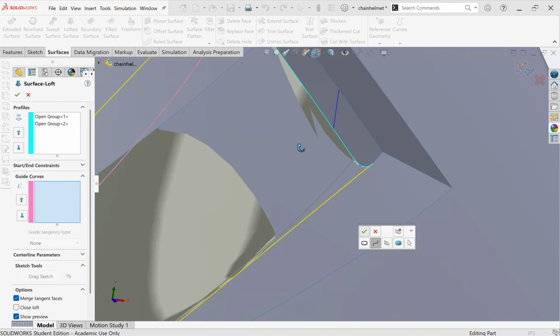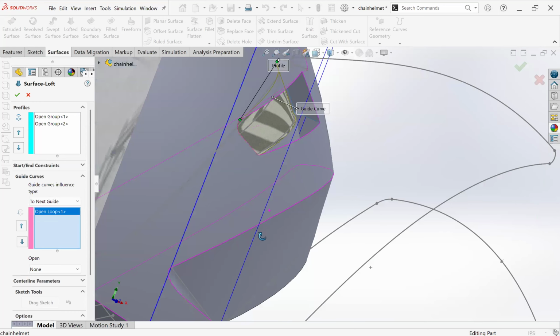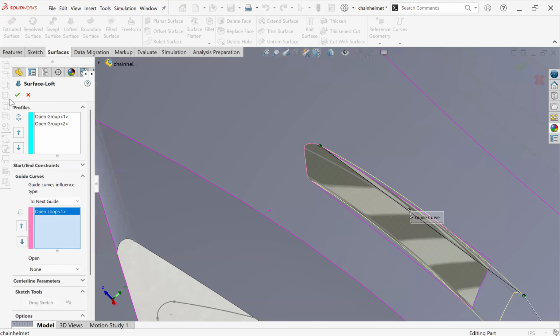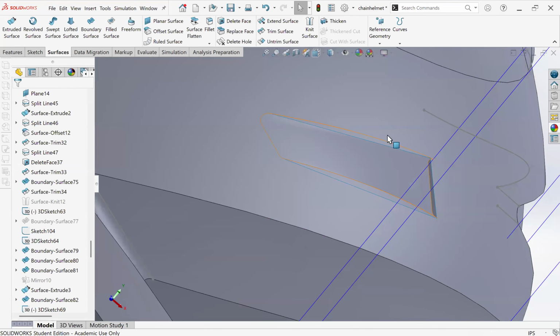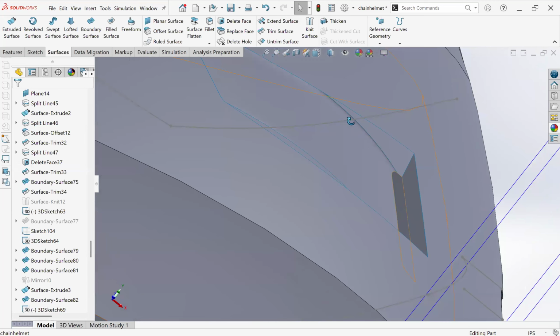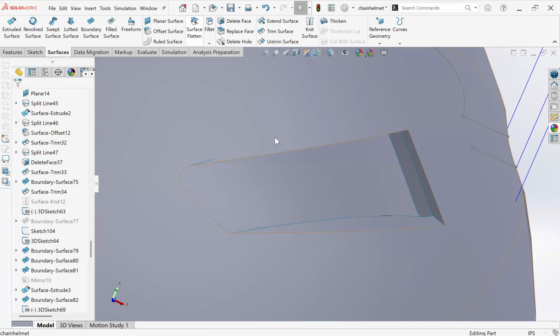Okay. I think they're selected. They look okay, good. Looks like that surface is not hitting. Perfect. And now that we have these two surfaces, we can fill the other one. Or we can do a loft and kind of have a guide surface there. I'm gonna try fill.